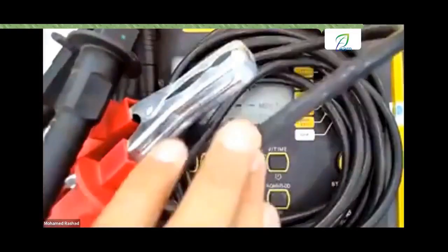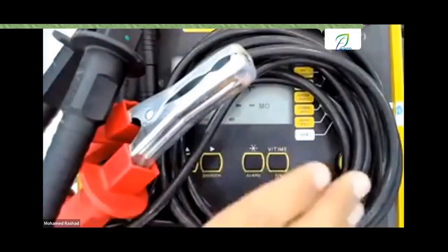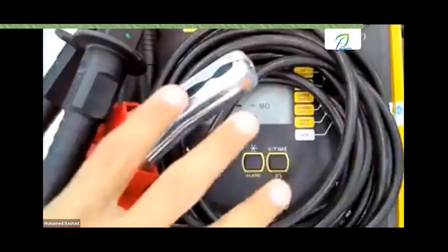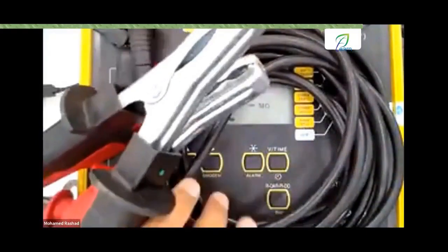Okay. Because of its insulation, of course, it might be on the ground or attached to the body of the GIS or the switchgear or whatever. So obviously there shouldn't be any leakage that affects the results. Therefore, your insulation here must be very strong. And you can't use any cables other than the ones that come with the device.